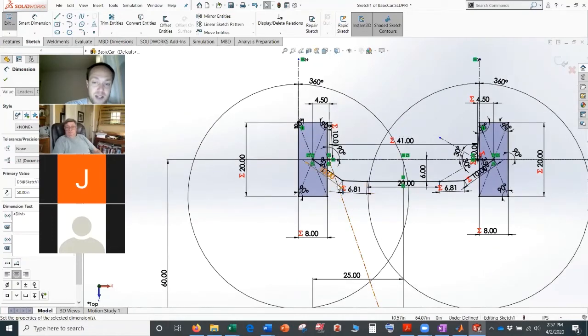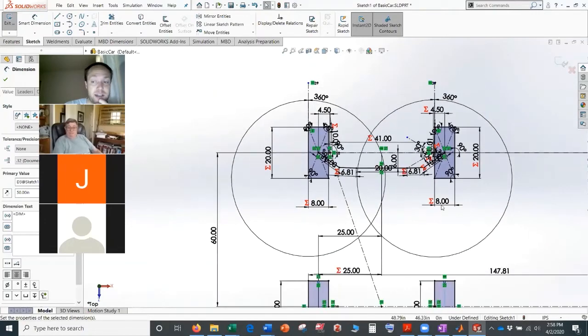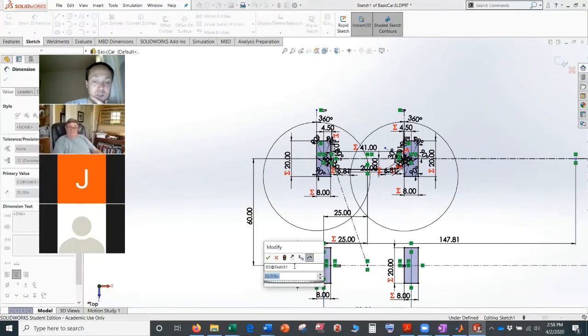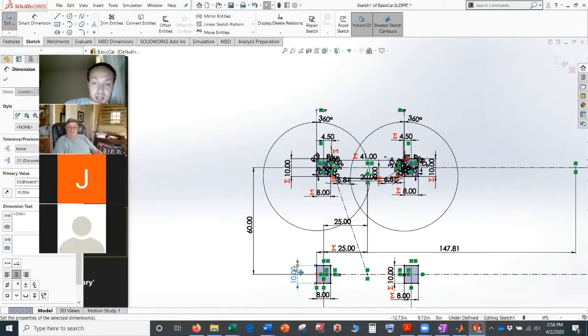And I put in a center line here so I could see that I'm in excess Ackermann right now, right? And on this side, I've drawn a 60-degree triangle so you can see if the side of our wheel begins to hit one of our arms, right? And the rest, like your tie rod length, it all gets calculated. So ideally you should make your SolidWorks models like this so that everything else is calculated. For example, if I change this tire, it'll change everything, right? And we'll probably find some stuff that's wrong with this.